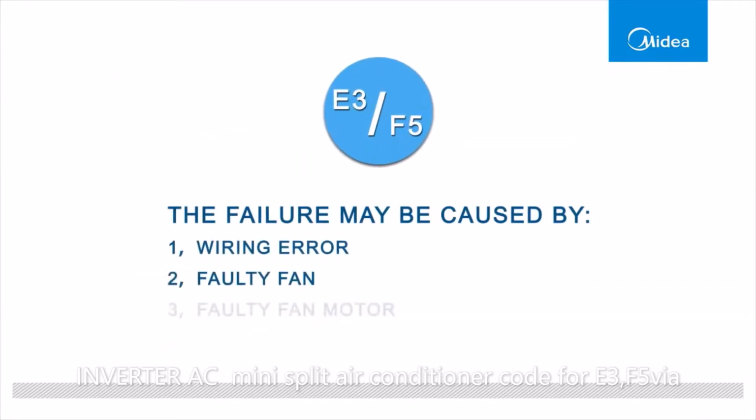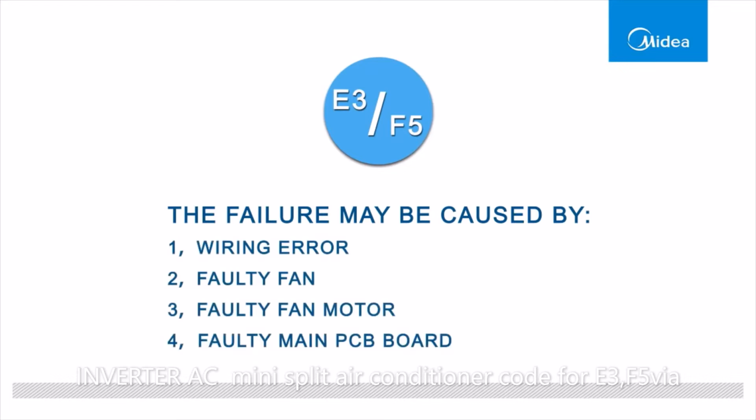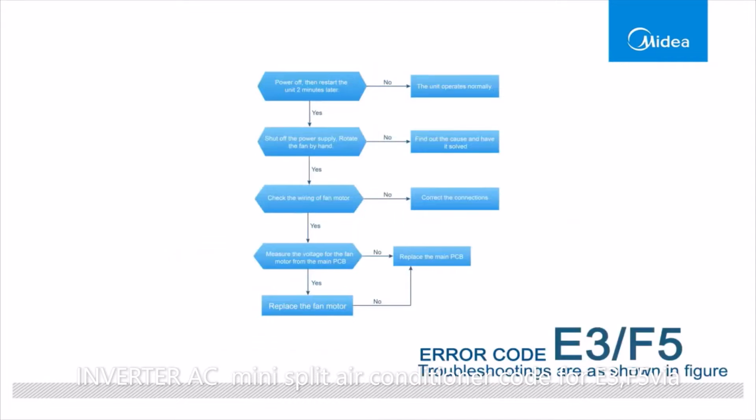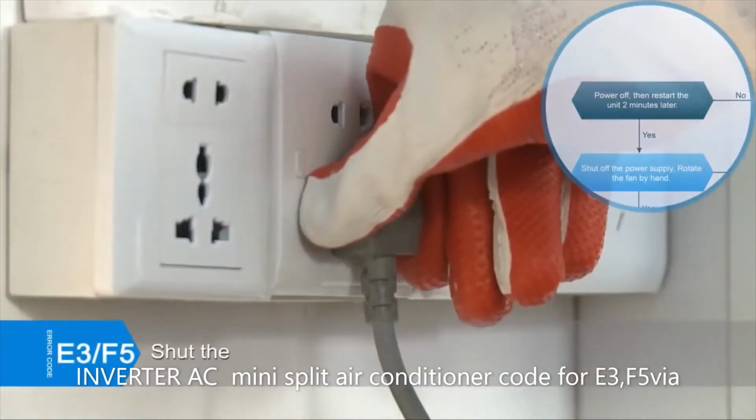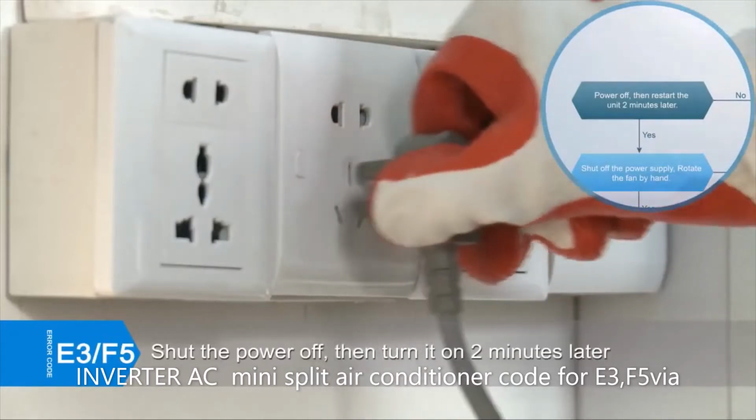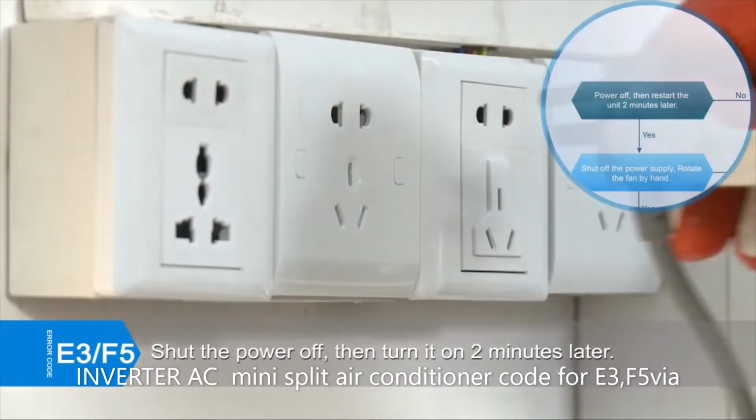The failure may be caused by: 1. Wiring error, 2. Faulty fan, 3. Faulty fan motor, 4. Faulty main PCB board. Shut the power off, then turn it on 2 minutes later.